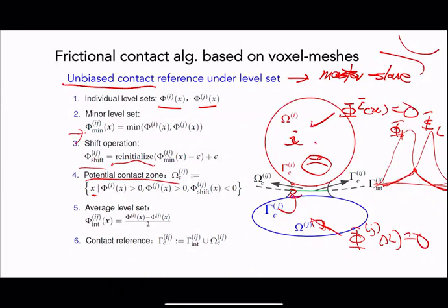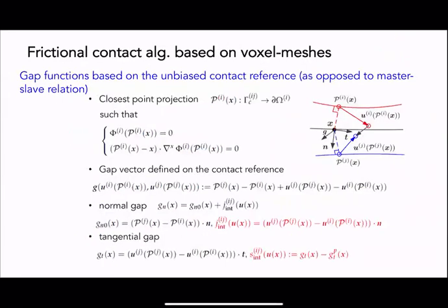This reference point for each individual particle tells us where the relative displacement is. As we change the displacement field, for each incremental step, we need to project this contact point onto the upper and lower surfaces, I and j. Then from the relative displacement of I and j, we can find the gap vector.